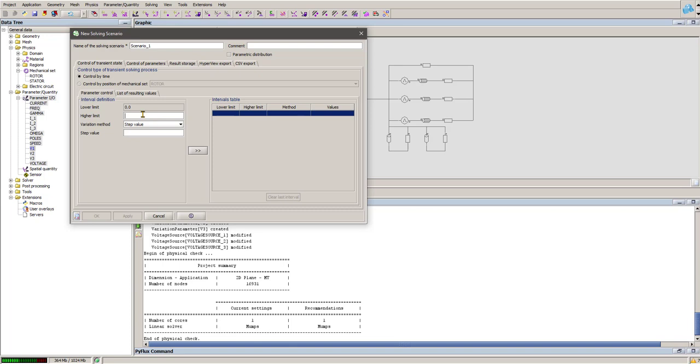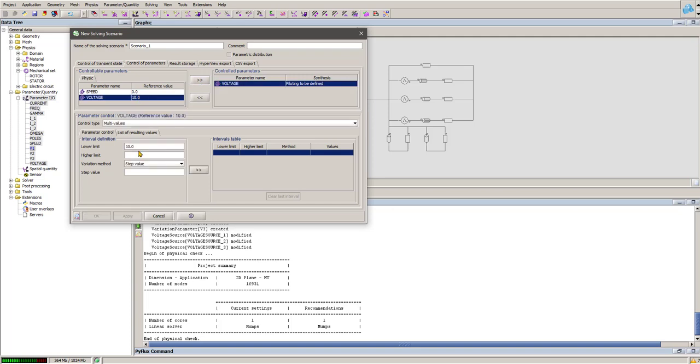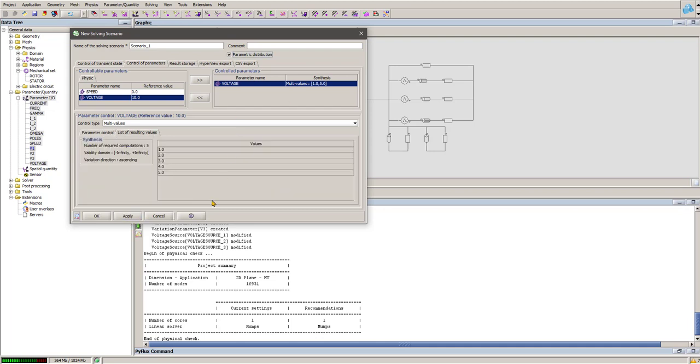This scenario I'm going to define is a DC voltage, so I just have to vary the time here. Let's say that I have 20 milliseconds and I want to reach scenario solving until 60 milliseconds, 3 electrical periods if we have 50 Hertz. But here again it's DC voltage, sorry. So let's make it like this, linear value, 61. And we can vary the voltage here, from 1 volt to 5 volt to start with. Apply. I can make a distribution.